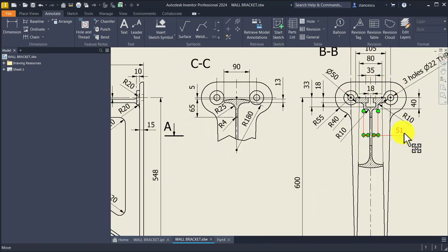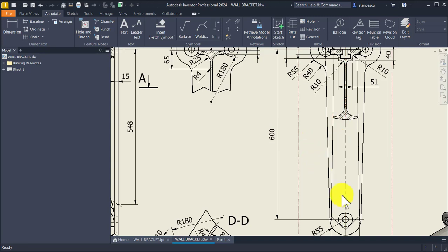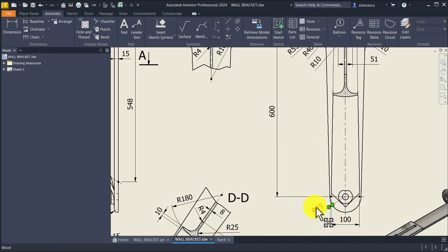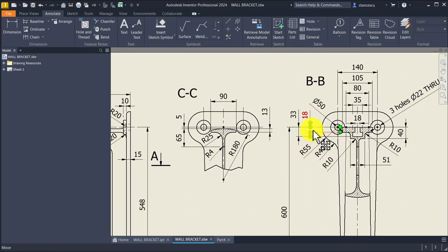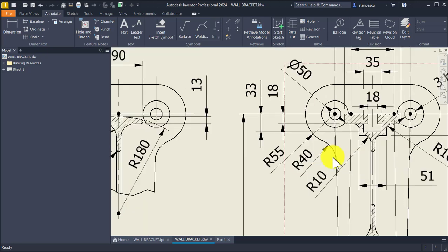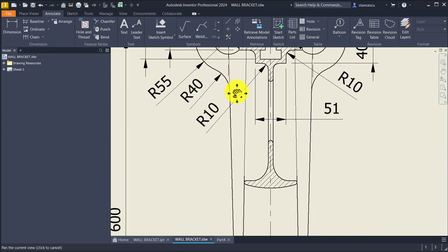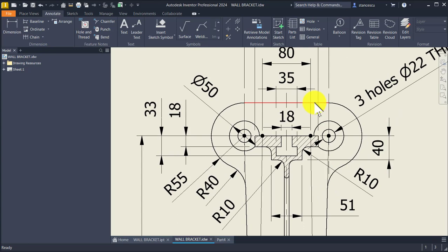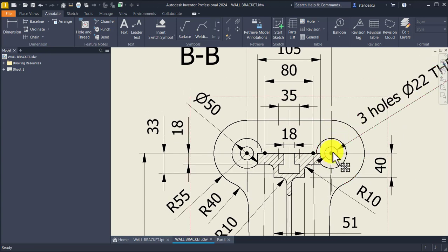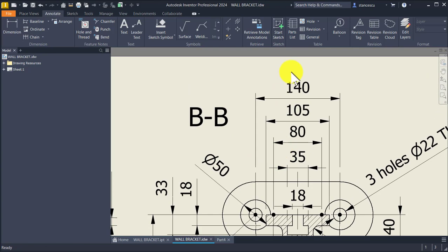As you can see, a distance of 600 between radius 55 and this with a width of 140, radius 55 again, a radius 40, and you must be very careful because these sloped sides are ended in these points at 140.